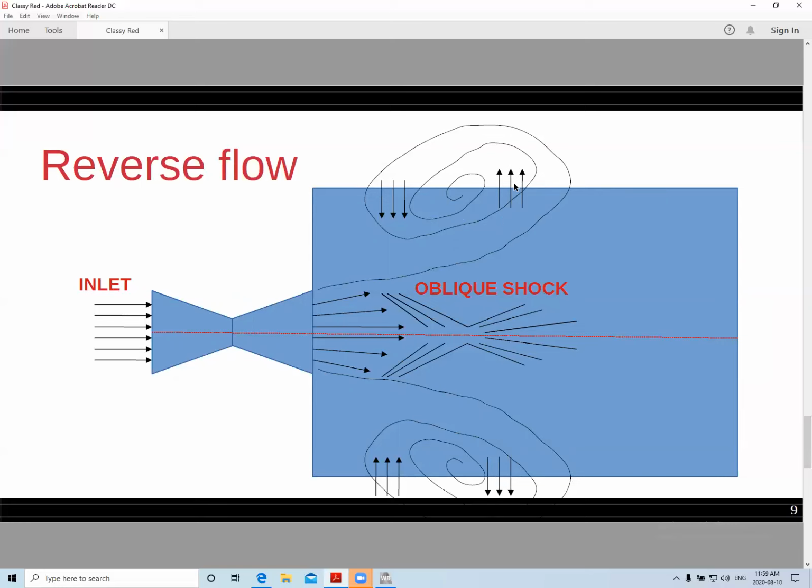Because it's a vortex, the flow goes out of the domain and again turns back into the domain. That's why you will get a reverse flow notice. It's something normal. It's out of your hands unless you make a really large tank.